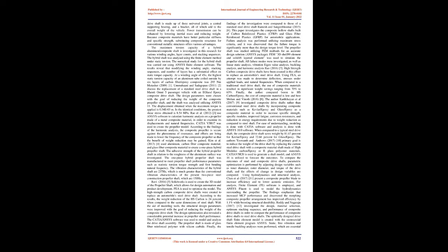The maximum torsion capacity of a hybrid aluminum/composite shaft is investigated in this research for various winding angles, layer counts, and stacking sequences. The hybrid shaft was analyzed using the finite element method under static torsion. The numerical study for the hybrid shaft was carried out using Ansys finite element software. The results reveal that modifying the winding angle, stacking sequences, and number of layers has a substantial effect on static torque capacity.